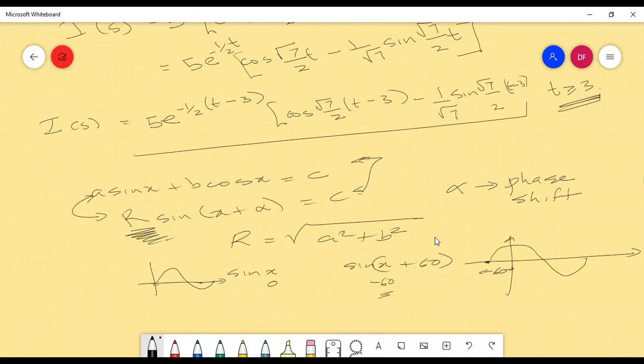So when you're looking at time t equals 0 over here for a system to be 0, you cannot look at time t equals 0 over here for the system to be 0 because the system has caused it to shift. So this alpha that you worked out in the maths problem is the phase shift through the system, how much the system shifted the wave. All right.